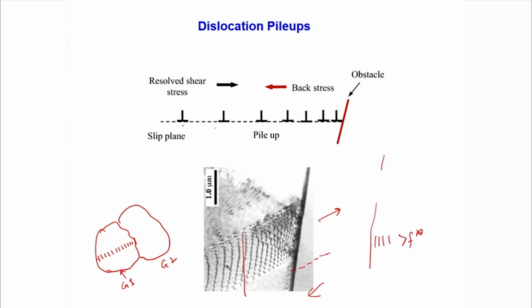And back stress is stopping them, or basically forcing them not to move on the dislocations, and therefore they need to cross over, or they need to be pushed by additional forces which is equal to the back stress plus the resolved shear stress. Okay, and that is leading to the strengthening of the material, right? So the extra force is extra strength. That is how it can be correlated, correct?